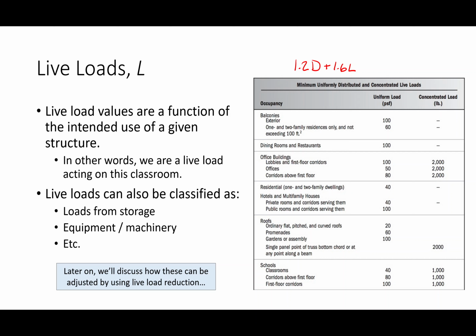Does that make sense? Now, let me ask you a further question, okay? If that's the case, why would we even have that load combo to begin with? I mean, why would we ever consider just dead load? If you're building structures to support people and support occupancy and support loads, why would we ever have a load combo that's 1.4 dead? When is a structure ever going to see just dead load? During construction. That's 100% right.